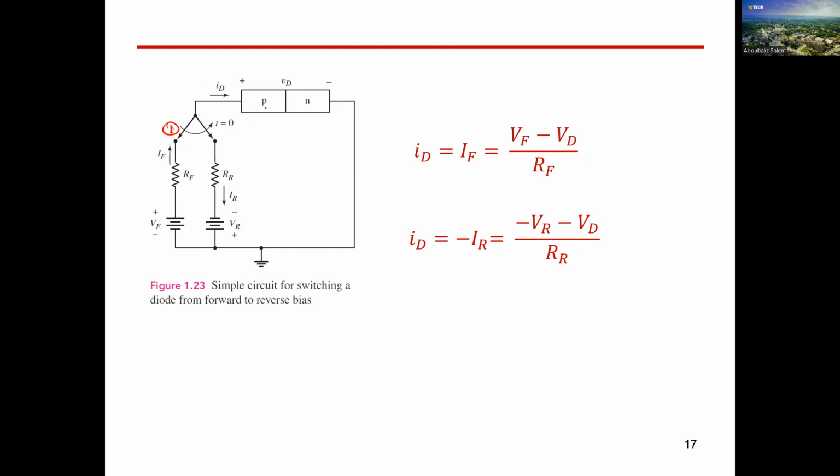So we can replace the diode, guys, by means of a resistance and a battery. So let's replace the diode together. The PN junction can be replaced like that. We have a battery, this is called the VD. This is a plus sign and this is a minus sign: plus on the side of the anode and minus on the side of the cathode. And then you have a resistance of the diode. Here in this equation, he called the resistance of the diode R, or even neglected the resistance of the diode, but practically you should have what's called R on, R diode on.